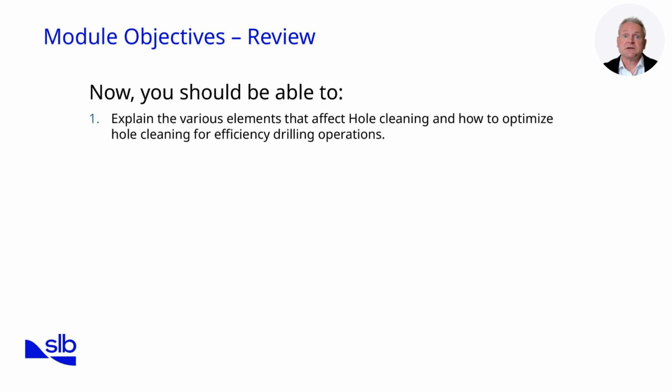This set the foundation for analyzing drilling fluid properties such as density, rheology, filtration, solids content, and chemical composition, all of which are critical in controlling hole cleaning dynamics. Next, we discussed optimization parameters, including annular velocity, hydraulic horsepower, and nozzle velocities, alongside operational goals: uniform cuttings distribution, stable wellbore hydraulics, efficient bit performance, and effective use of surface horsepower.